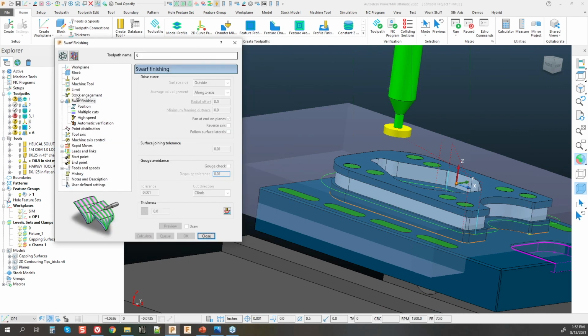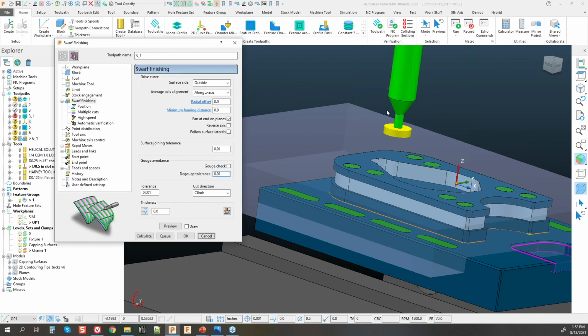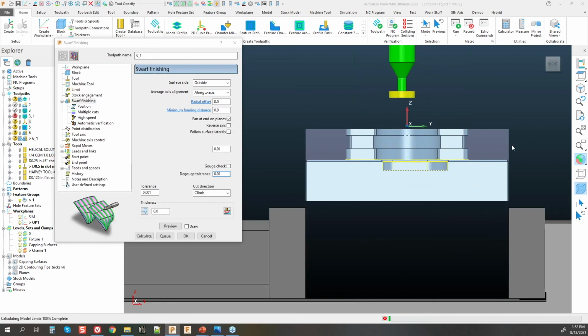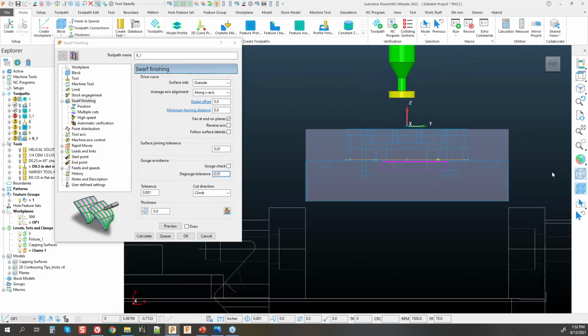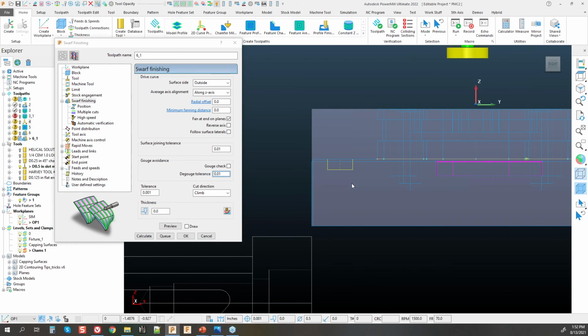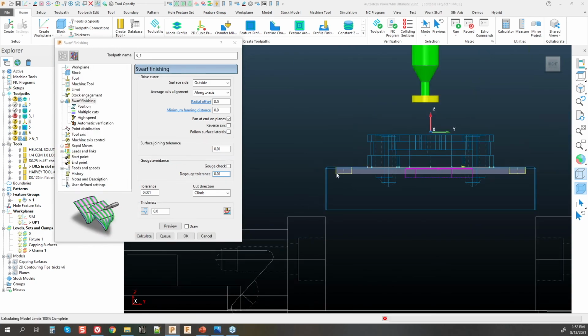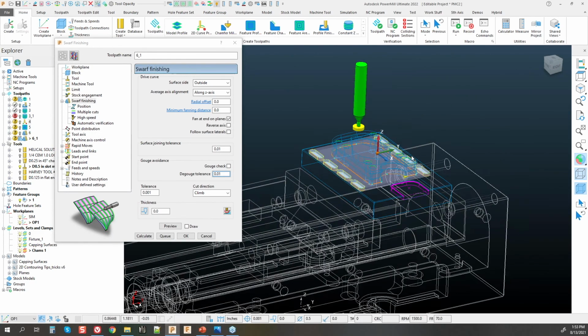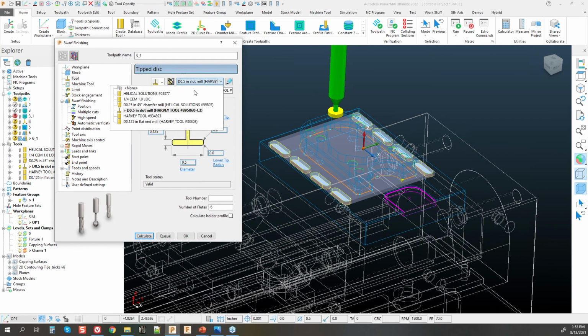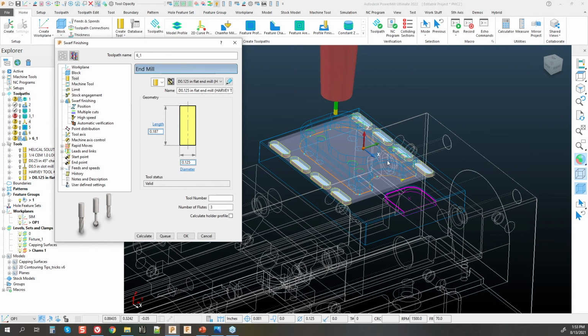Now, the other reason why I like using swarf, again, is multiple features, such as the pockets that we have here. So I'm just going to go ahead and shrink wrap my block around my part. I'll go into wireframe view here, and I'm just going to select these pocket features. Shrink wrap the block around those. I'll change my cutter so that I can get a successful slot out of this. Let's go to this little tiny 1/8 inch end mill here.